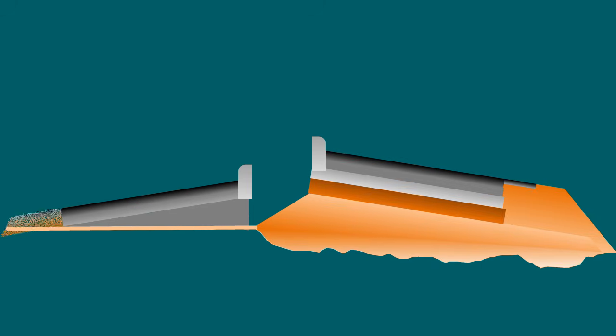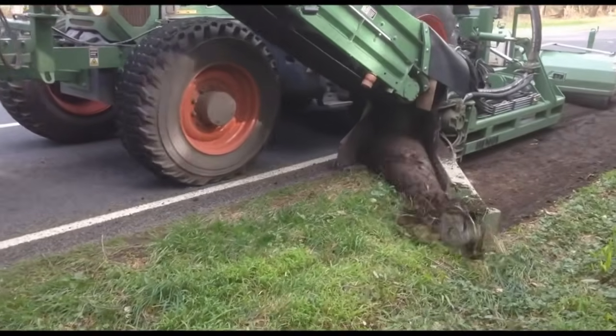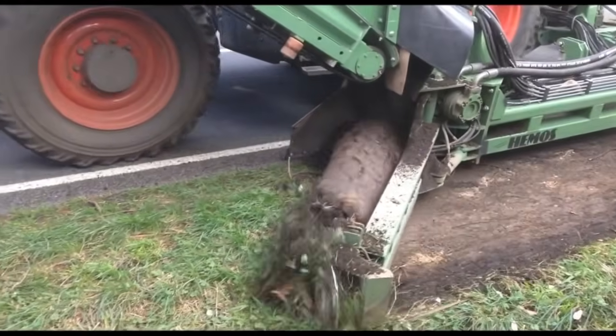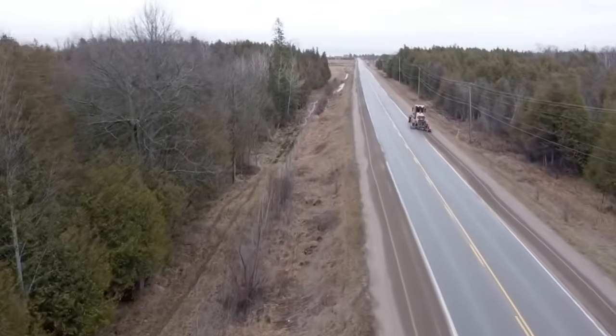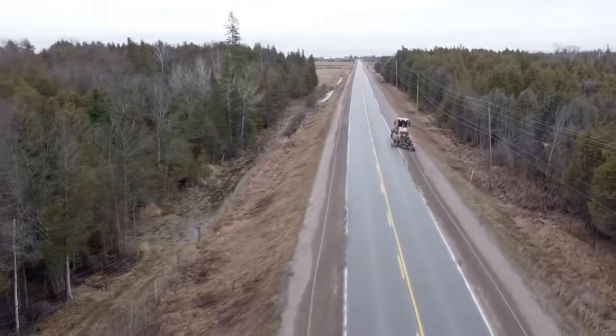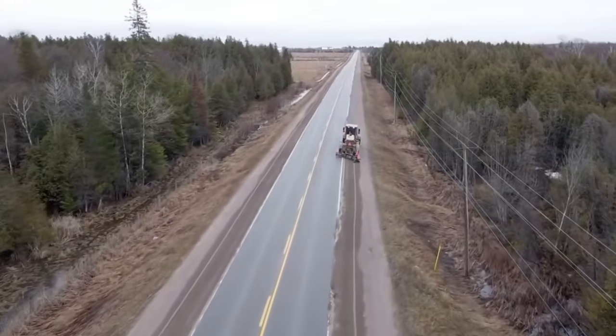Next item of work is shoulders. The shoulder is a necessary part of highways, and it serves several functions. It serves as a lateral support to the highway pavement. It provides a means of protecting the highway surface from the intrusion of water, which is one of the great destroyers of our highways. A wide shoulder provides a temporary parking area for people who wish to stop and enjoy the scenic vistas so readily available.